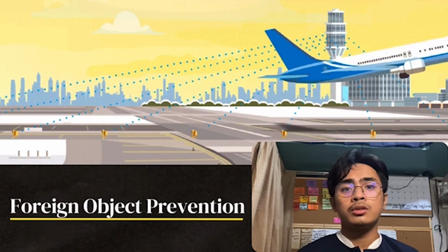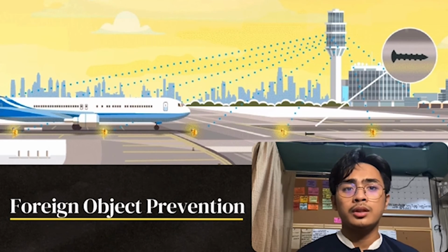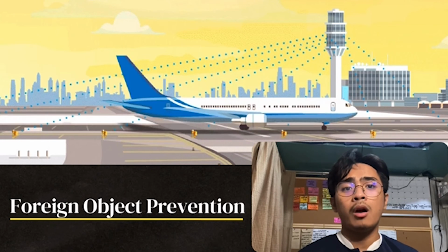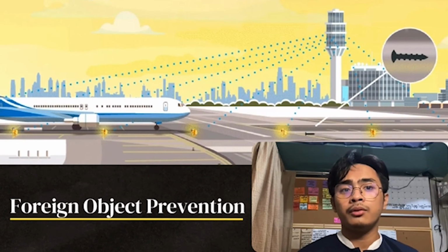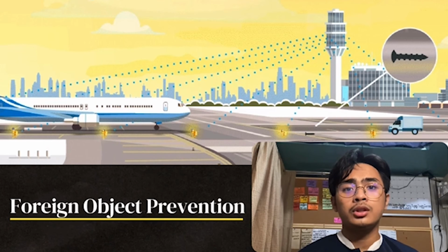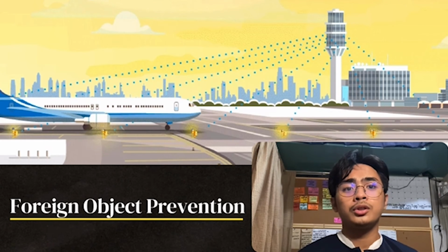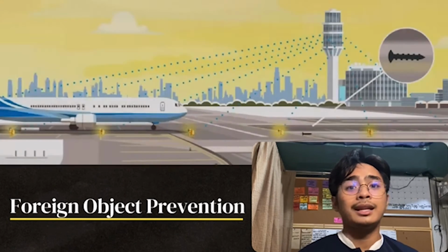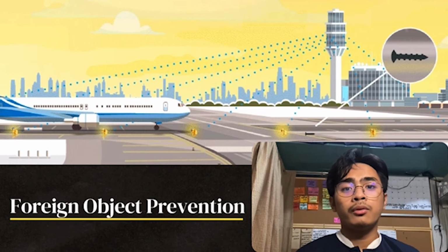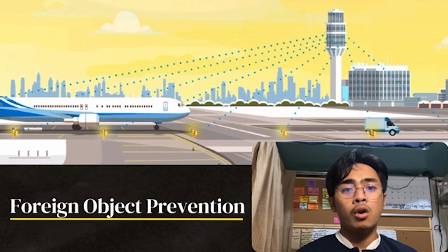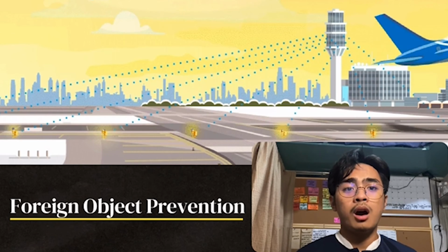Fourth is that we should ensure ground and surfaces on which aircraft or aerospace vehicles and ground support equipment are operated and maintained are free of objects that could cause damage due to ingestion or due to jet blast effects. And lastly, we should report foreign object damage incidents or potential incidents to prevent unwanted circumstances.